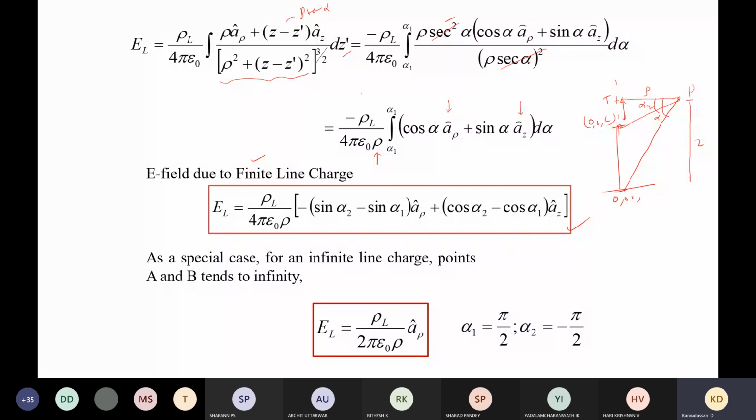When the length of the line is infinite, okay, if the particular point is here, origin is here, no matter whatever the location of the particular point be, we can always assume that it is going to be almost in the plane of the origin itself. So along the XY plane, it is going to be kept, and therefore let's say we take arbitrarily 2 points. Those 2 points, we are going to take arbitrary points at, let's say, Z1, and this is Z1 dash. Both are available at the same distance.